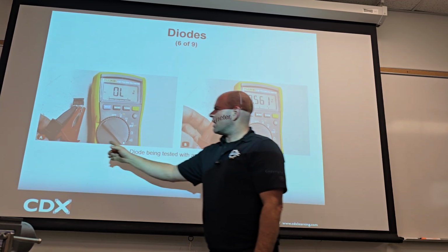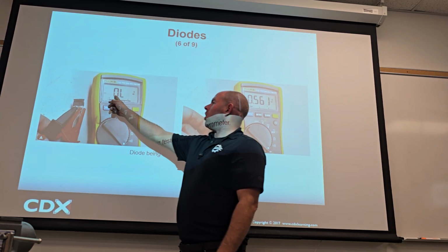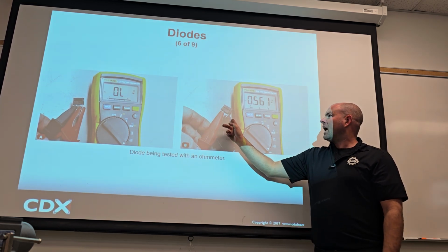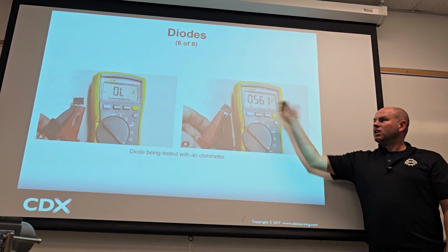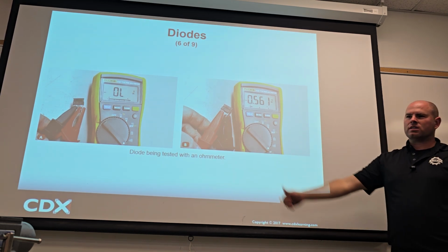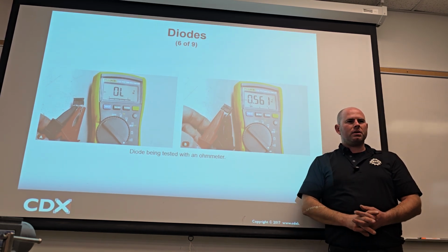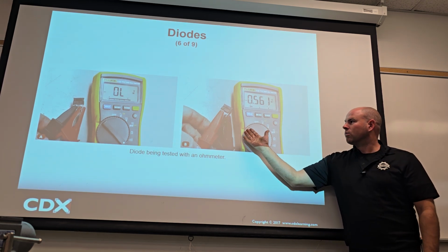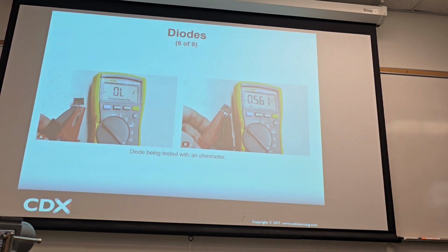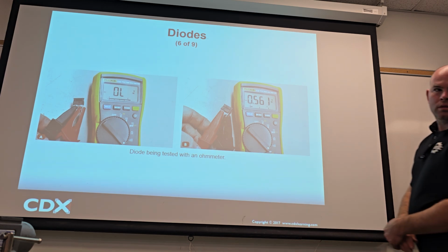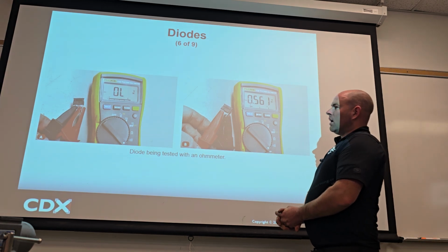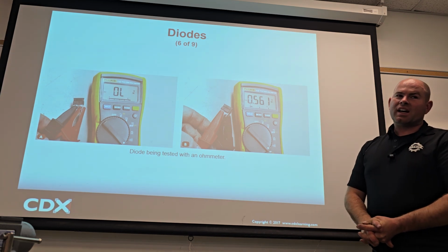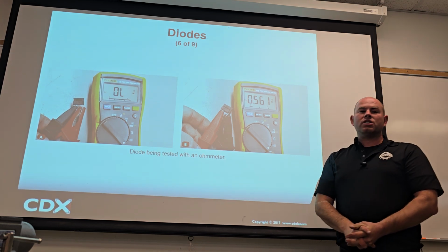When we put on the diode test, we do black, red, and it says open. You flip them, red, black, and it says what? It does flow. Make sense? So this diode would have passed right here. That would be good. It blocks it that way, but it allows it that way. Just like what we said. The forward bias voltage is 1.6 for a diode, at least in this example. I'm not sure exactly what it's going to be in each case.